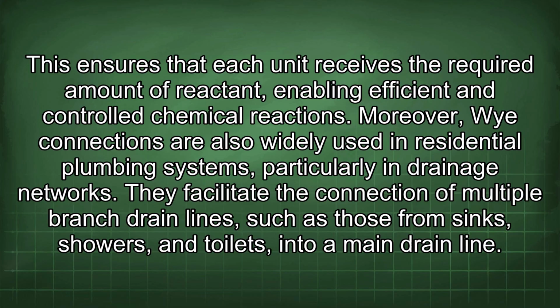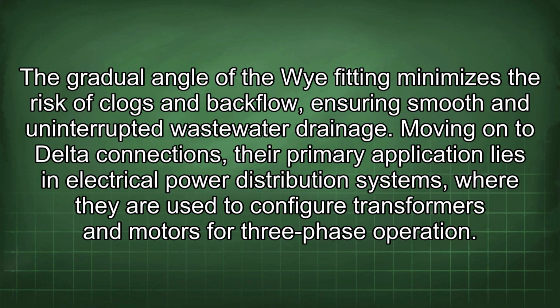Moreover, Y connections are also widely used in residential plumbing systems, particularly in drainage networks. They facilitate the connection of multiple branch drain lines, such as those from sinks, showers, and toilets, into a main drain line. The gradual angle of the Y fitting minimizes the risk of clogs and backflow, ensuring smooth and uninterrupted wastewater drainage.